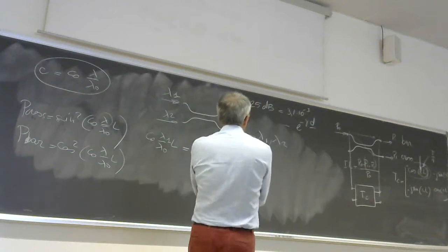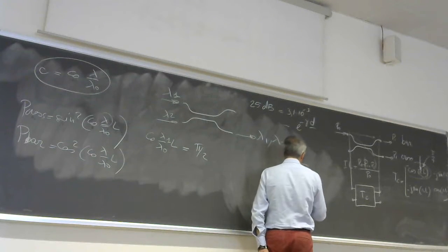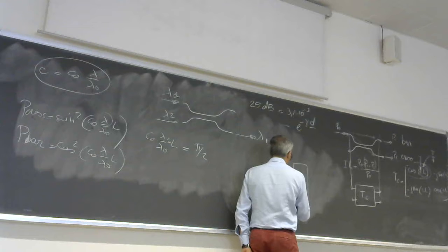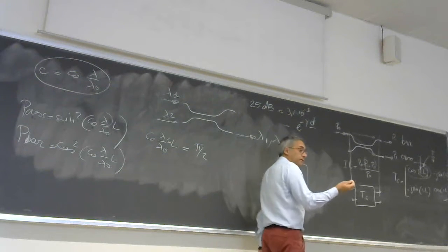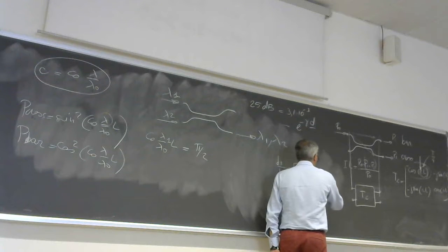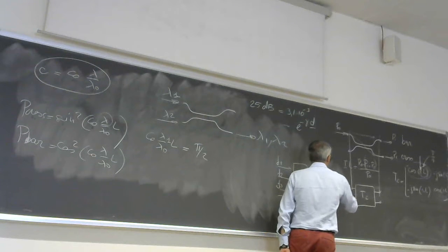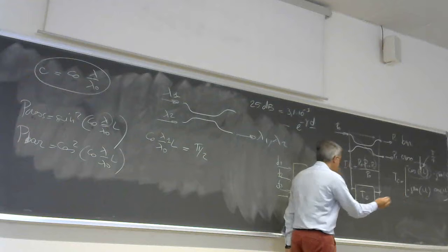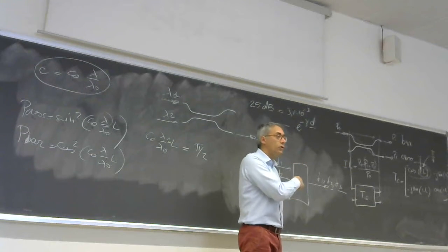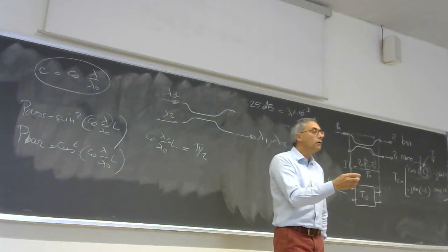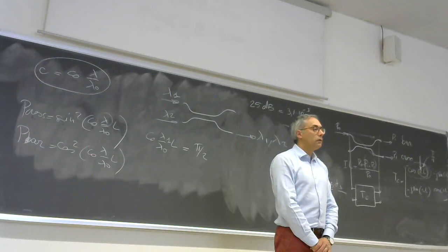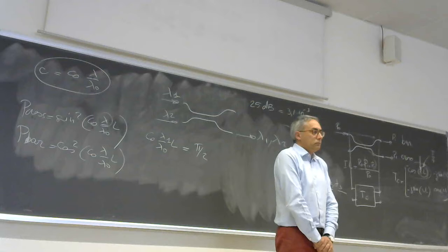How do you call a device where you have several signals that enter at different wave frequency or wavelength, and one output, and all the signals at the same time exit from this port? Multiplexer. But usually in a multiplexer, we had a port to choose which of them goes out, not all of them. It was an electronics multiplexer.